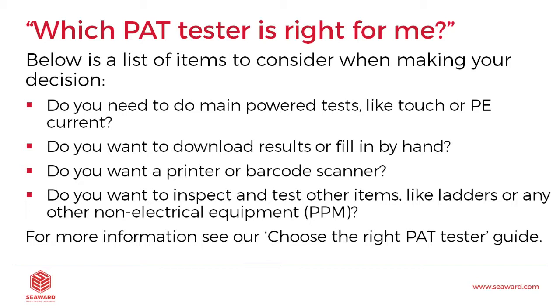We typically tend to say if you're looking at anything above 300 assets, and that's a big number, do you want to be filling in things by hand? You'll spend as much time filling out forms and writing labels as you would be doing testing. So again, consider that the initial cost and investment may be higher than a manual tester, but in the long run, if you're testing a number of appliances, the downloading facility will very quickly pay that back in no time.